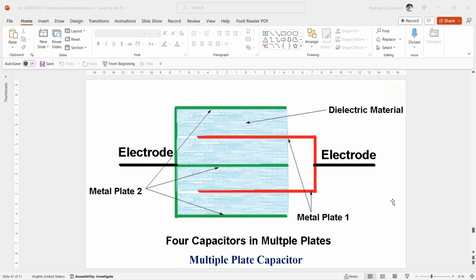The signal transfer from the transmitter to the receiver is determined by the configuration of the electrodes and shows a triangular course with displacement. Also realized with simple technology like PCB, copper electrodes, and coating, the resolution of the sensor appears to be about 126 nanometers over a range of 20 millimeters.